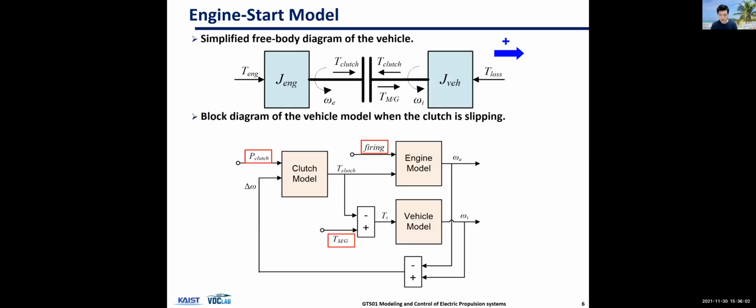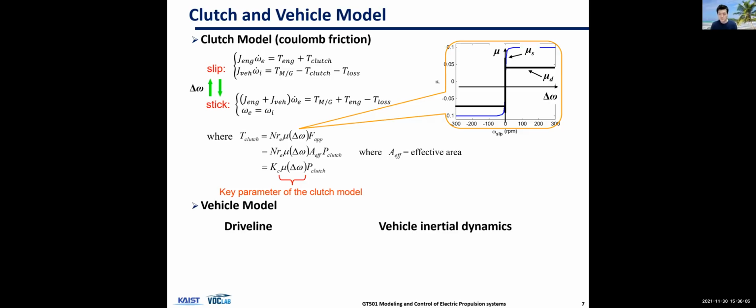And what I mean by that is near zero slip, we are using this approximated clutch model, so we need to apply large torque to create friction. Okay, because for zero slip speed, the mu also becomes zero. It goes across this zero value. Okay.